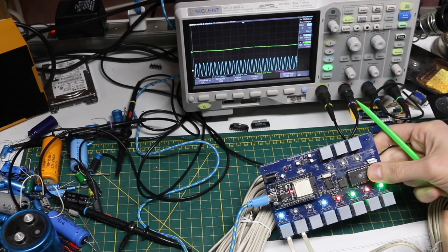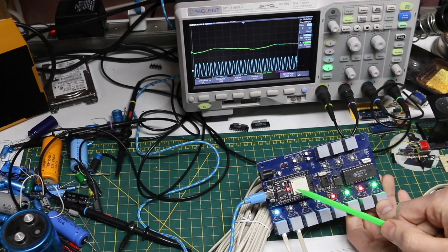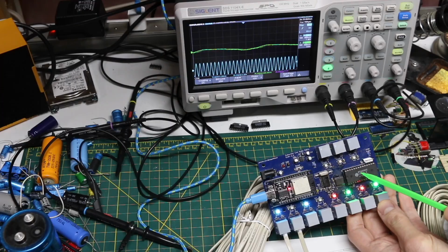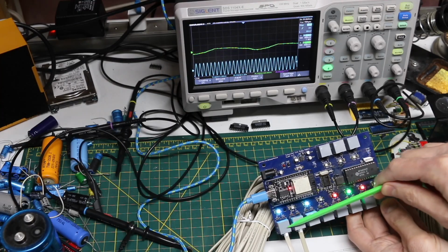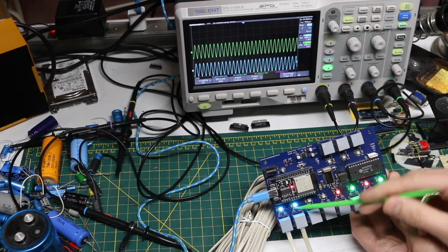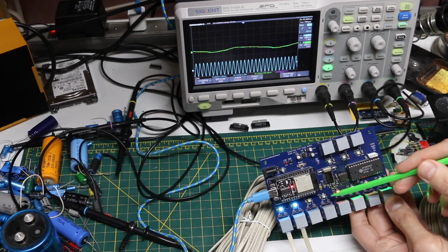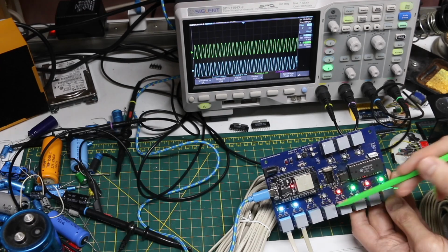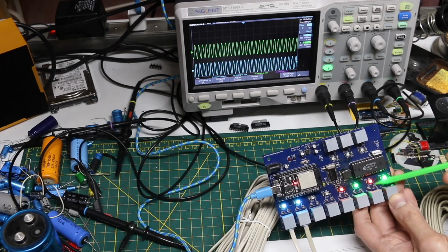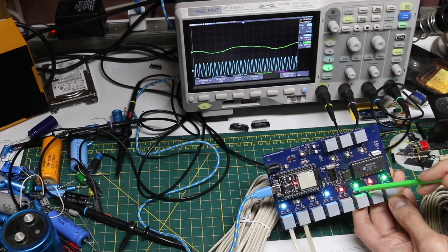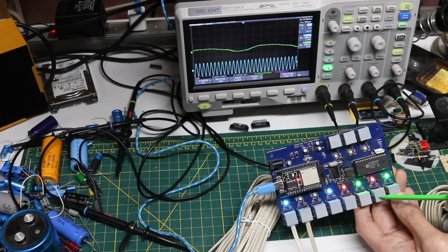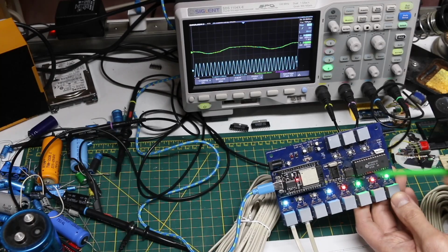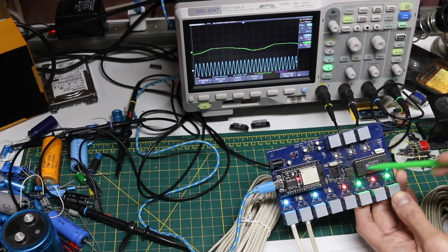So here's what's going on in the board. I've got software in the ESP to control the MT8808 matrix to route audio between various channels here. So the LEDs light up to show in different colors any channels that are in common. So over here I have 2 red ones and then 2 green ones. So that means if I plug a phone cable into both red ones, it's always passing audio right through. And the same with the 2 green ones, it's always passing audio right through.